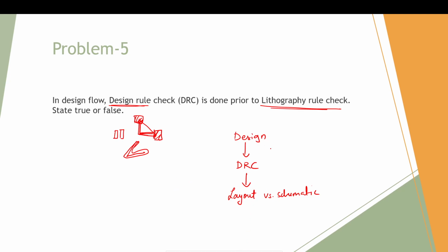You will usually check all these things at the design stage itself, but after this you will also do an optical proximity correction, OPC. In your layout, even though you might be within the critical dimension, so the DRC might be passed, say the critical dimension was 0.5 micrometers, in some places everything is close by, at a distance of say 0.5 microns, but in some other places things are like one line, sparsely populated.